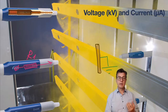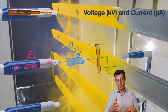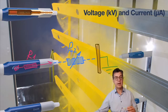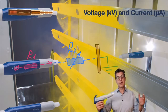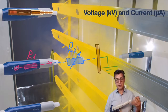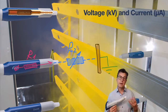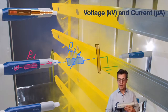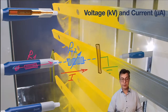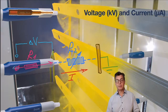Well, to complete the circuit, we need to also draw the resistance of an air gap between the gun and the part. And this is shown here as resistance number 2. That resistance changes as we move the spray system closer or farther away from a product we're trying to coat. Once we've ionized air and created corona discharge, the space between the gun and the part is populated with millions of free-flying charge carriers, and the current starts flowing through this circuit. As we said, the current flows through this circuit, and every time current flows through a resistor, a voltage drop occurs on that resistor.